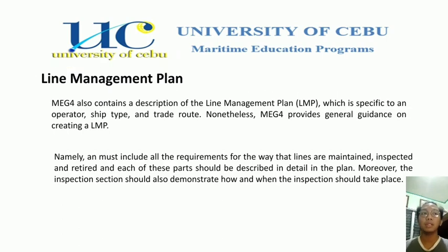MEG4 also contains a description of the Line Management Plan, or LMP, which is specific to an operator, ship type, and trade route. Nonetheless, MEG4 provides general guidance on creating an LMP. Namely, it must include all requirements for the way that lines are maintained, inspected, and retired, and each of these parts should be described in detail in the plan. Moreover, the inspection section should also demonstrate how and when the inspection should take place.